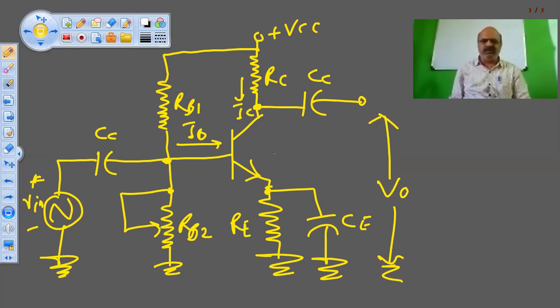So this type of arrangement we call an amplifier. This is common emitter because emitter is common. How is the emitter common? Because you may say you have connected a resistance on the emitter side. Now how can the emitter be common? Yes, for DC signal it is not common because the emitter is raised to a higher potential than the ground potential, because we have connected a resistance RE in between the ground and the emitter.